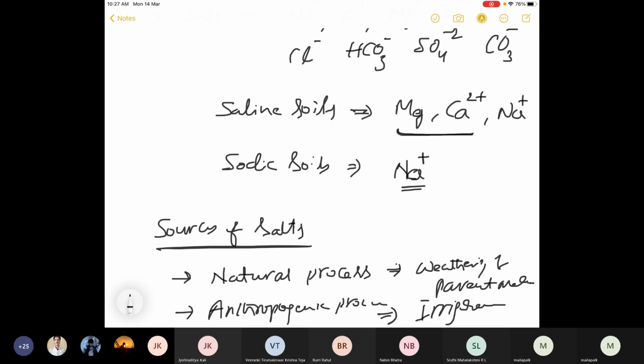Okay, so according to WHO, up to 500 ppm is safe for drinking. So he comes and checks. Okay, so your TDS is around 600 ppm. So you need to change the filters, or you have to go for the reverse osmosis process, the filters with an RO system and all. He will suggest a lot of things. So that's the quality of water, right?